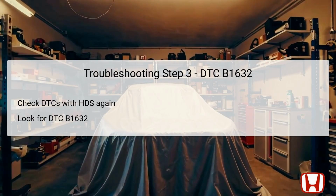If DTC B1632 is shown, it confirms the persistence of the issue, warranting further investigation into the related components such as the keyless access control unit or electric steering lock. If this DTC is not present, it suggests that the problem may have been an intermittent failure, requiring checks for loose or poor connections instead.